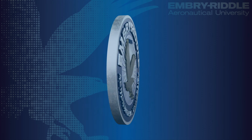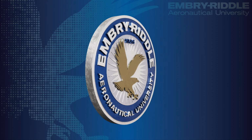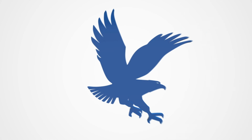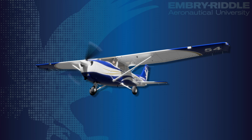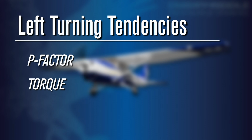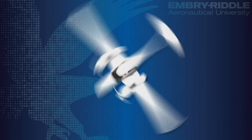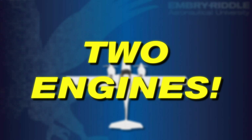Now that we have compared the four forces acting on a single-engine and multi-engine aircraft, let's look at another significant aerodynamic factor: left-turning tendencies. On single-engine airplanes, predominant factors contributing to left-turning tendencies include P-factor, torque, and spiraling slipstream. These same factors affect multi-engine aircraft as well, and the resulting effect is significantly greater because there are two engines.